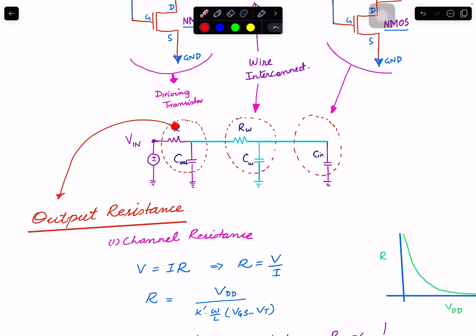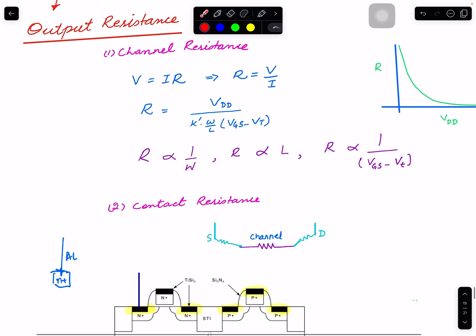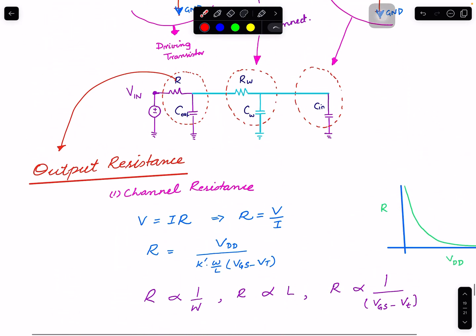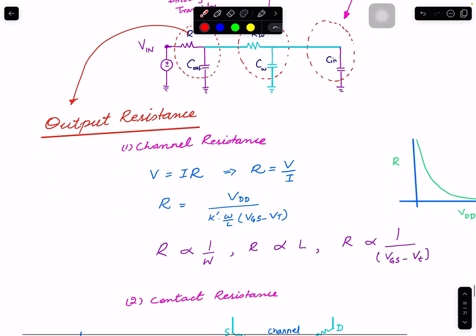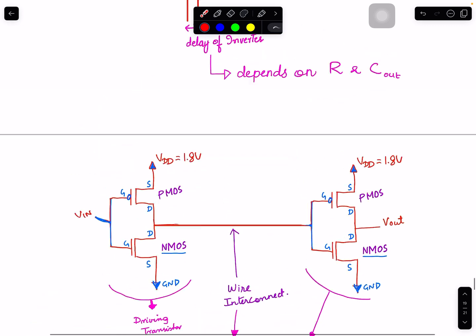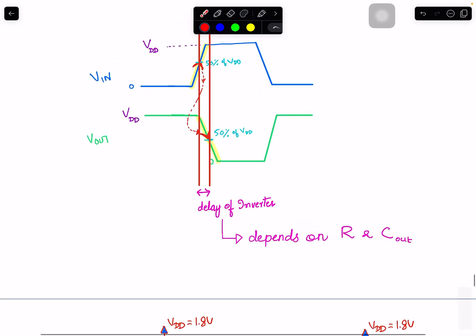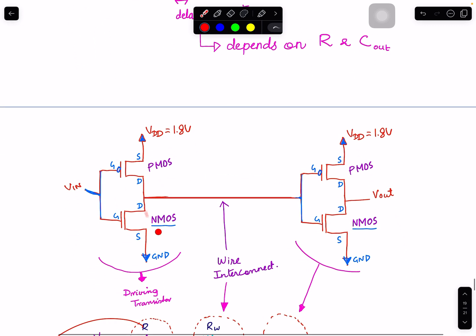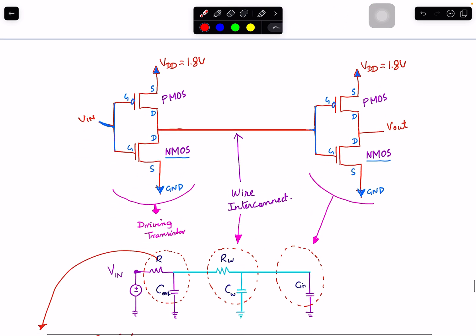And the resistance of the 2 components I told you, and the voltage that is coming here, and then you can solve everything. So those are the resistance and capacitance components and how they affect the delay. I told you the delay definition is from 50% of the input to 50% of the output. This is how it will later come up in static timing analysis as well. So I thought it's good to give you that overview. Keep resistance and capacitance down, and that will be good for delay. Okay, hope you understood that.